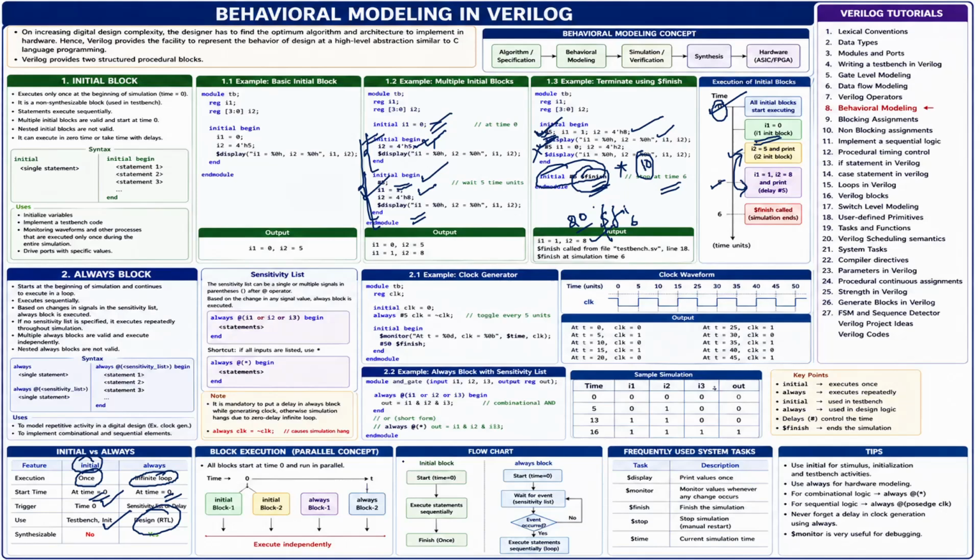So this is the behavioral model, and I told you the initial block executes at time 0. This is the flow of execution. Now about initial begin and always: don't use multiple always blocks. We use multiple always blocks in the design code: one is for combinational circuits, that means always @(*) is used for combinational circuits. You can use a single combinational always @(*), and don't use multiple always @(*) blocks. Also there is always @(posedge clock) or negedge reset, which we use for flip flops. That means sequential execution. So for sequential blocks we use always @(posedge clock), and always @(*) we use for combinational circuits.